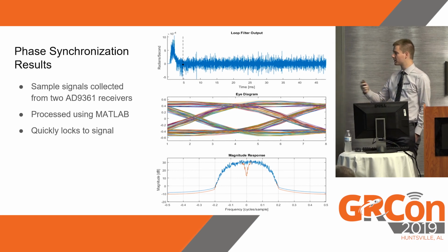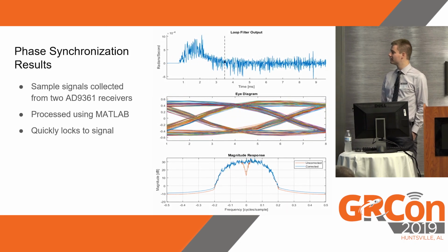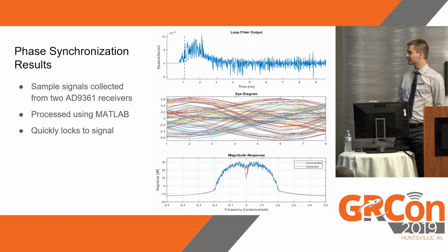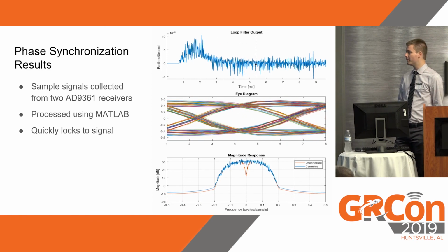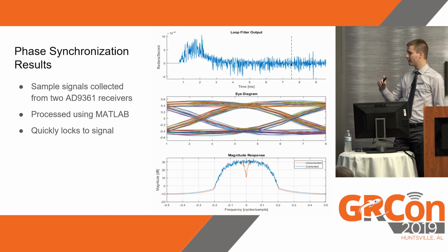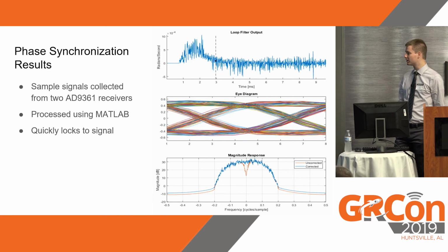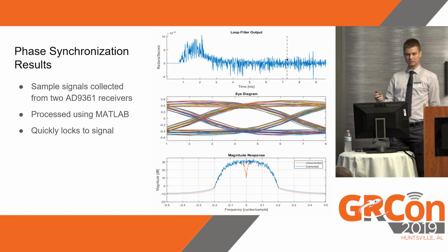We implemented the whole algorithm and simulated it in MATLAB. And you can see here, when we start out, it very quickly, within a couple of milliseconds, locks onto the signal. You can see, initially the eye diagram is just a complete mess, but it very quickly sorts out those phases so that the signals are added coherently. And you can see that also in the bottom here, where the orange signal is the combined signal using no feedback.